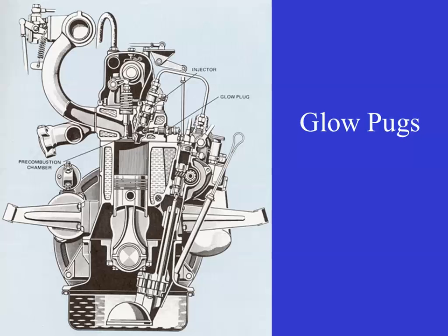Glow plugs are not used very often on marine engines. I really haven't seen them, but it is an auxiliary starting method. Who I do know still uses those today is Mercedes diesels, but the glow plug now is in the main combustion chamber. I don't believe they still use a pre-combustion chamber.